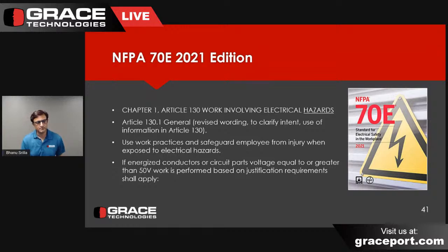So basically, they're still harmonized, but it's a major cleanup, right? And very focused: do you need the permit, yes or no, the exemptions, then move into the shock risk assessment and the arc flash risk assessment. And again, this is where we start to diverge, on the arc flash risk assessment. If you do not have incident energy analysis completed, you have method 2, the arc flash PPE category method.